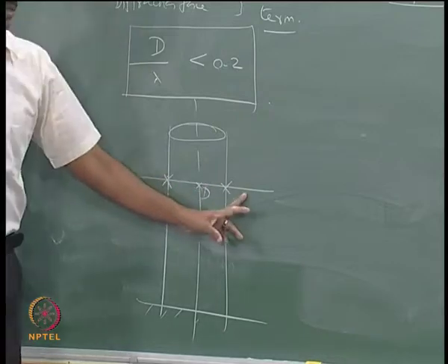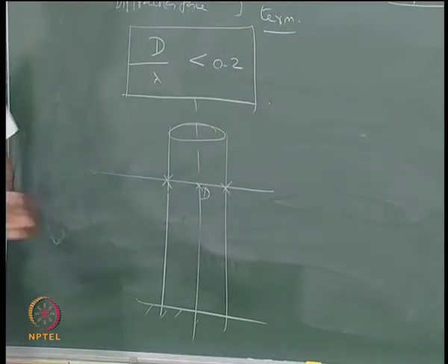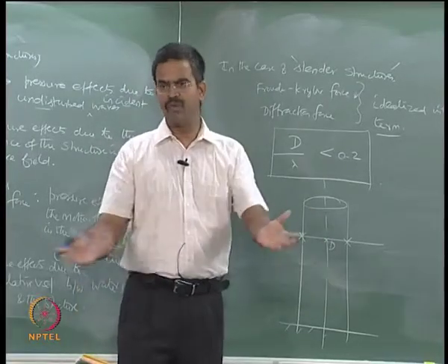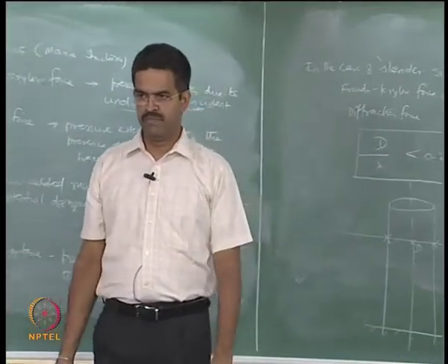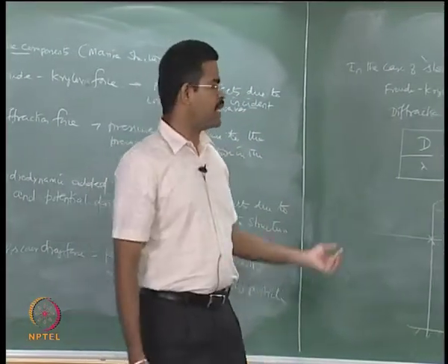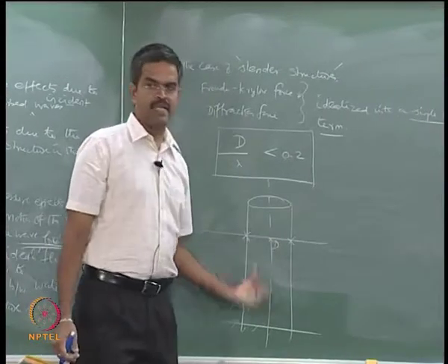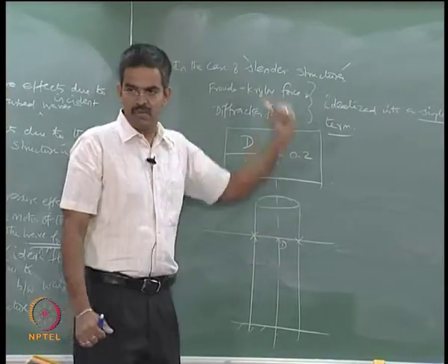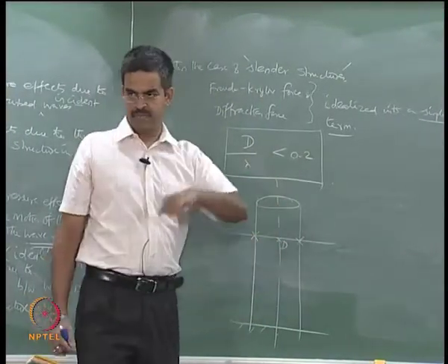Between these 3 points, the velocity and acceleration or the water particle kinematics will not vary much. So, for all practical purposes, the member can be idealized as a single line member along its axis.